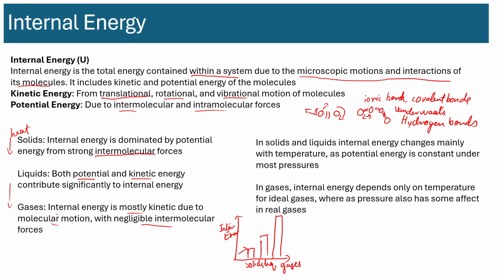In solids and liquids, and in all scenarios, internal energy is mainly a function of temperature. You might wonder, why can I not increase the internal energy of molecules by adding pressure? If I add pressure, I'm doing a lot of work on the fluid. Doesn't it cause an increase in either the kinetic energy or potential energy? The answer is no in most scenarios.